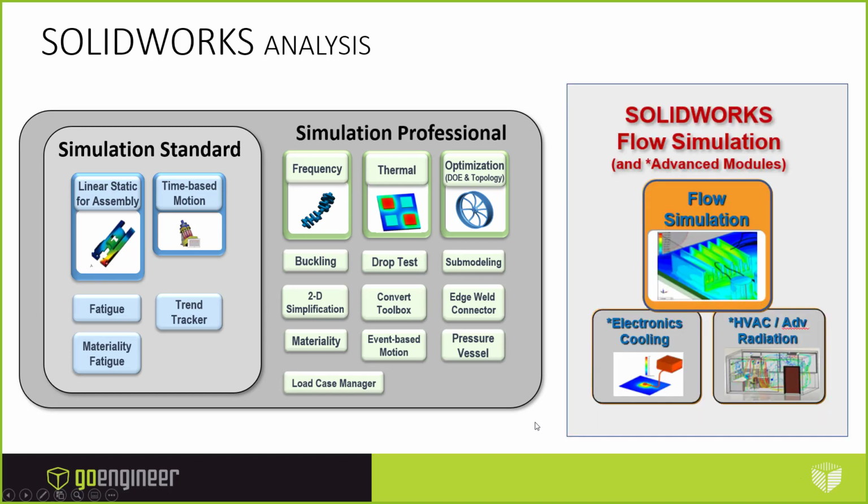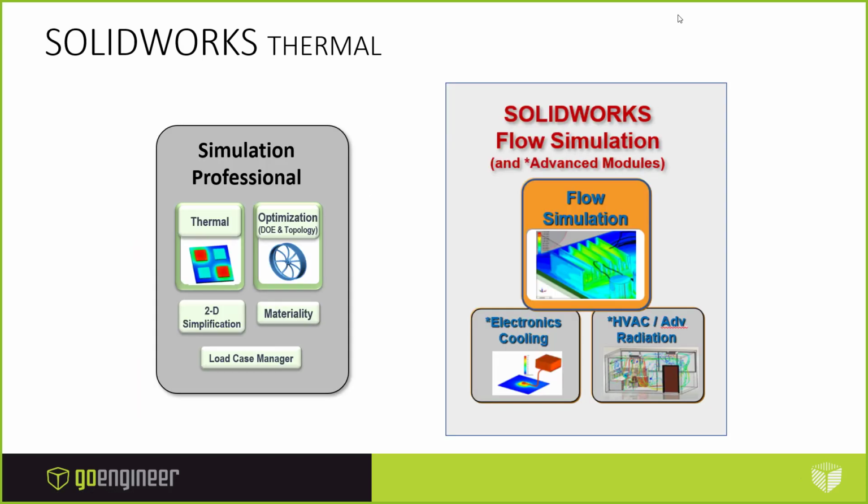Then on the side we have SOLIDWORKS Flow Simulation. Now this is a package that's sold separately from these packages. Simulation Pro doesn't include the SOLIDWORKS Flow Simulation, but this tool here as well is capable of thermal analysis. So really we're going to focus this presentation down on this little subset here, specifically the thermal analysis available with SimPro versus the SOLIDWORKS Flow Simulation, and see how those results stack up.